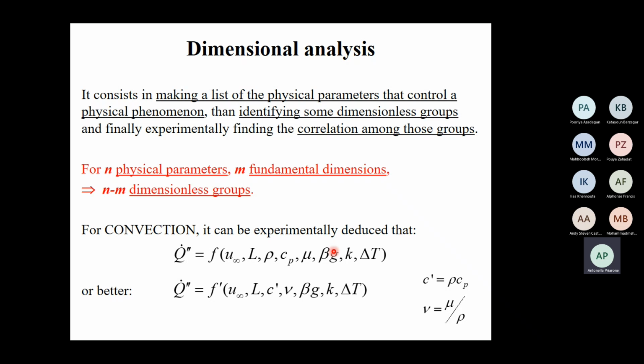In natural convection, the motion of a fluid is due to the buoyancy forces. The buoyancy forces are the forces created in a gravitational field when I have zones of a fluid at different temperatures. If I have a zone of my fluid with higher temperature locally, I have also lower density. You know that the density depends on the temperature.